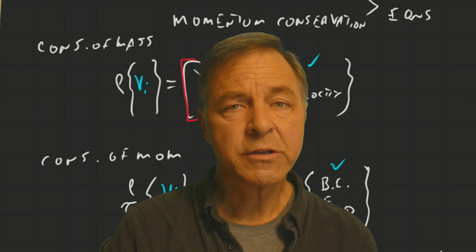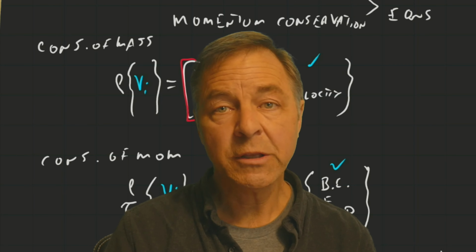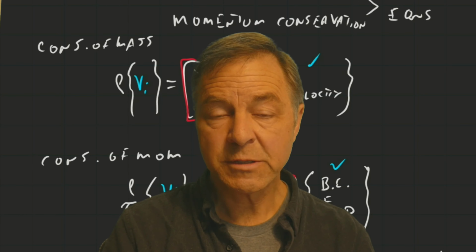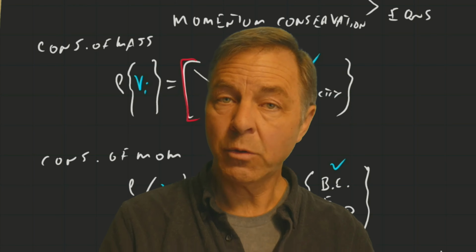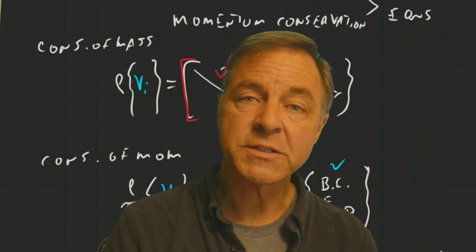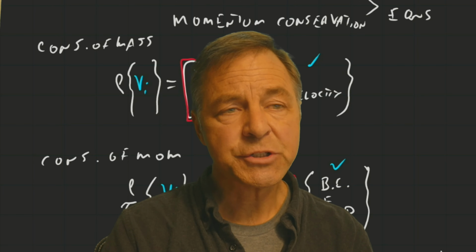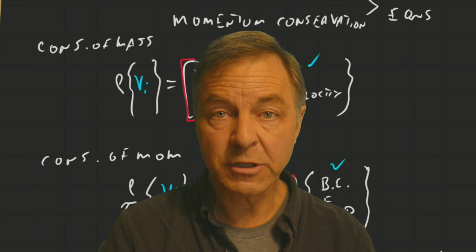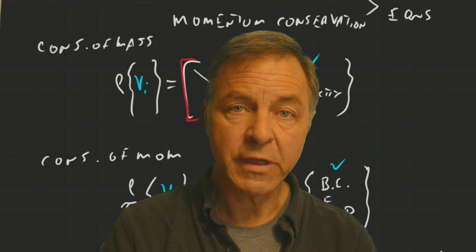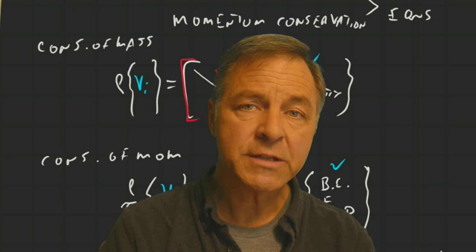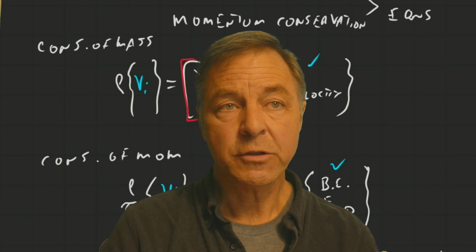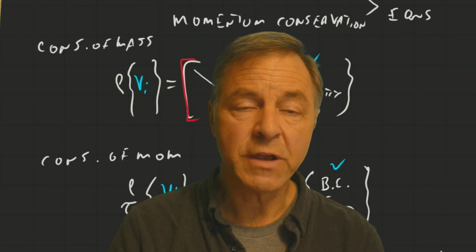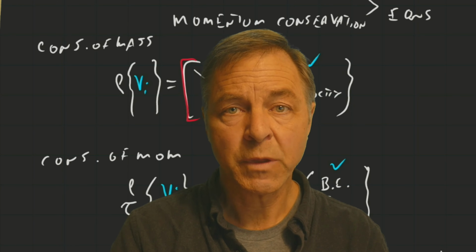So those calculation problems are really, really important. And as you can tell, if you just sat down and did one simulation, you would have maybe thought, oh, that was correct, and moved on, when in fact it's not. Flow simulation can lead you down the garden path very easily. You have to learn to be very skeptical about it, and also to prove that it's working correctly. And even in cases that are simple and you believe are working correctly, you still have to be very cautious and be very careful about proving that that's the case.